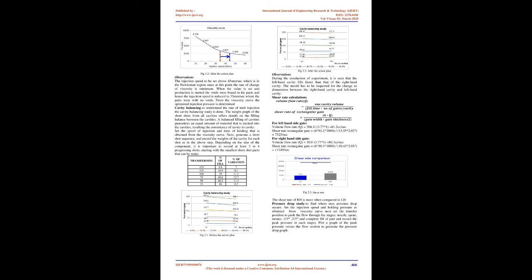The value is 10. Observations. The injection speed is to be set above 45 mm/sec, which is in the Newtonian region, since at this point the rate of change of viscosity is minimum.